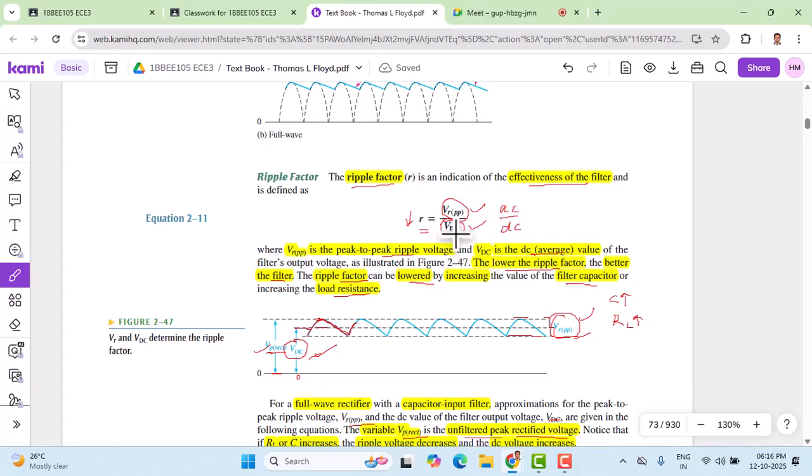There will be 5%, sometimes 3%, 2% AC variation, but the circuits which require fully DC can have a tolerance of up to 10%. That's how circuits are manufactured. Though it expects completely DC, it can still tolerate 2 to 3% variation. We can't expect 100% DC in any conversion process.